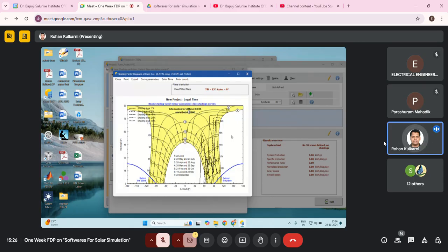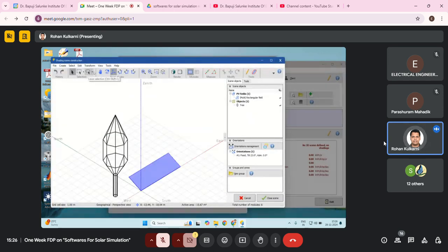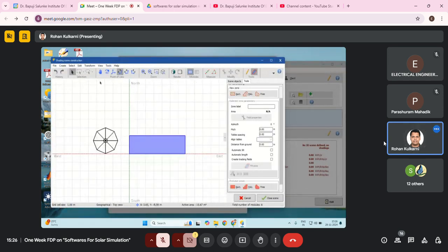If there won't be any shadows in summertime, it's good. But if due to some objects there is shadow on your panels in winter, then first, as I mentioned, it gives you lesser output. Second, the important thing, the dark spot effect, is problematic for your system. So let's see, I'll keep this particular object out of the way so that we get the maximum.